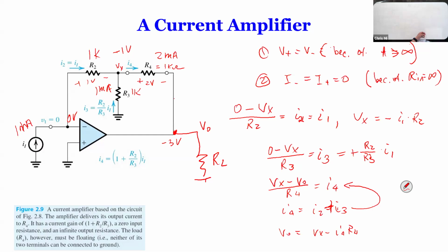Now, this amplifier has to be nearly ideal because it has to have a very large input resistance. Otherwise, you lose all the input. And we have to have a very small output resistance because you want all the signal that you amplify to be usable. You don't want anything to be dropped inside this amplifier. Very useful.